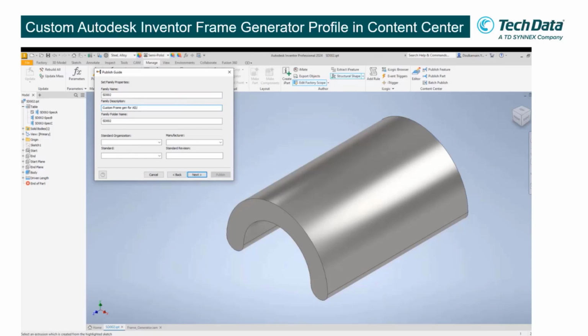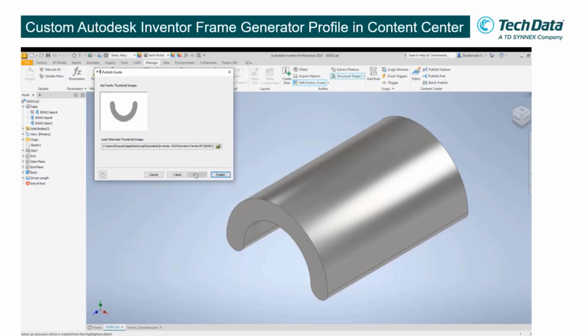Frame gen. Okay. All right, and then family folder, so we can create a new family folder name. If we want to, we can add the standard organizations, or let's say we want to customize the standard organization, we can also do that since this is a custom component. Let's just use our organization name as the standard organization. Okay, to publish, and then publish completed successfully.